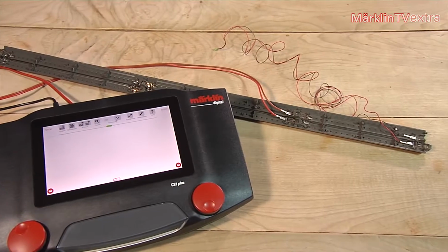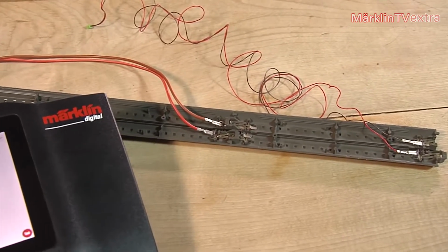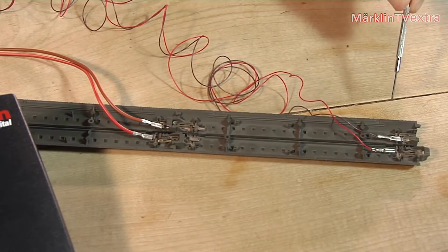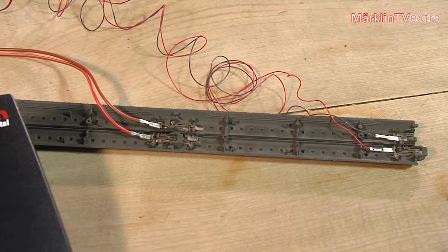The signals were designed to minimize the amount of wires and cables that need to be installed before the signal is ready for operation. This also means the decoder is already mounted inside. What is left to be done is to plug in the red and brown wires. They ensure the current supply and the digital signal. The first steps take place at the programming track, which first needs to be connected to the CS3. These 2 wires directly connect to the signal.